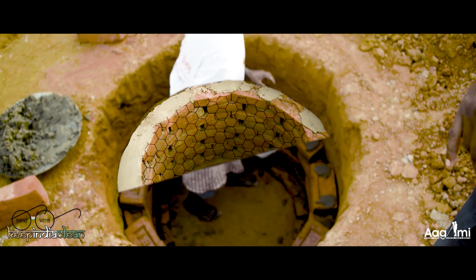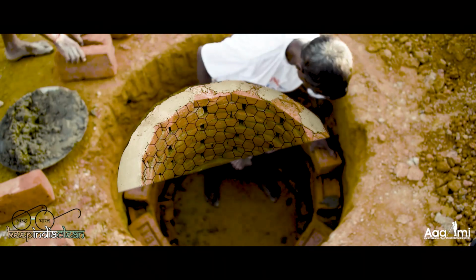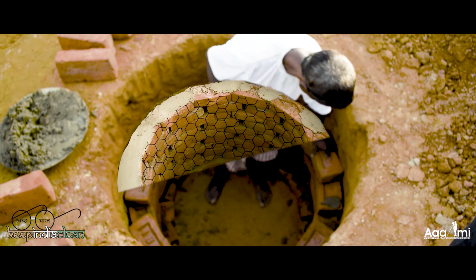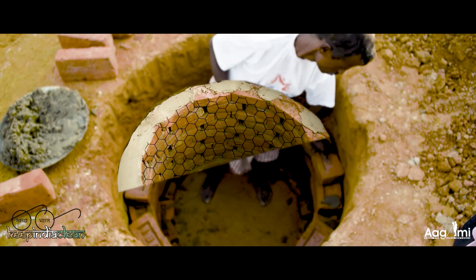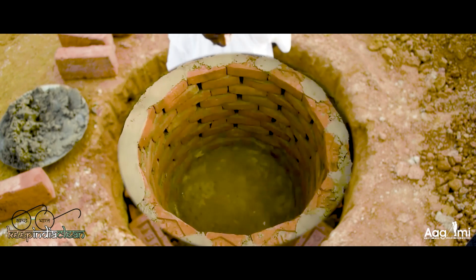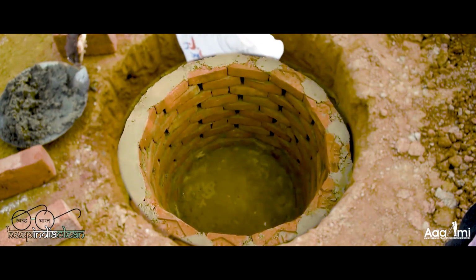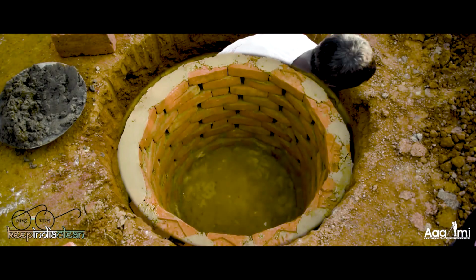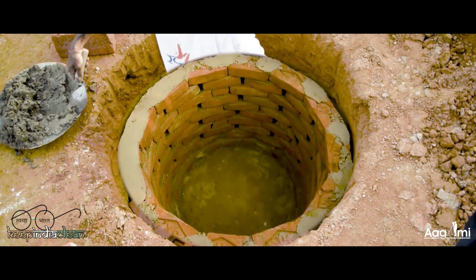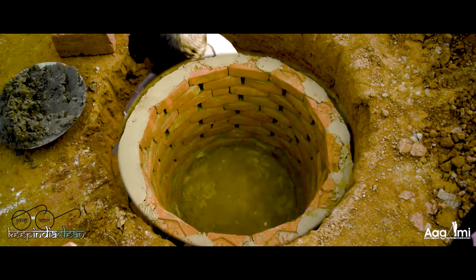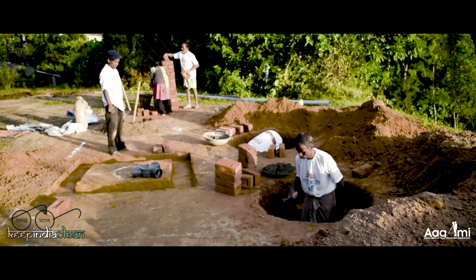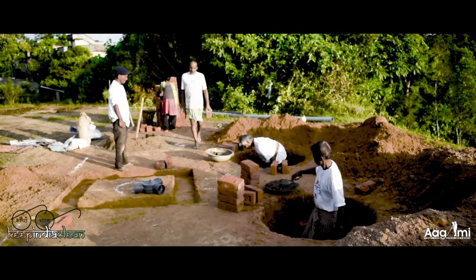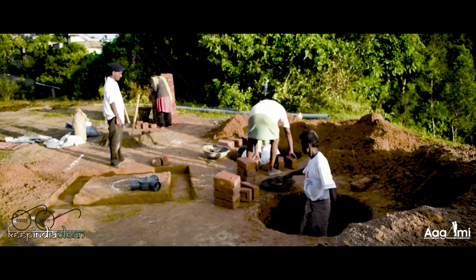The liquid part of the faeces is absorbed into the soil through these holes. Further, the microbes can easily enter into the pit to decompose the solid residues into manure. The size of the holes depends on the nature of the soil. The holes are usually small in loose soil, whereas they will be larger in case of harder and rocky soil.